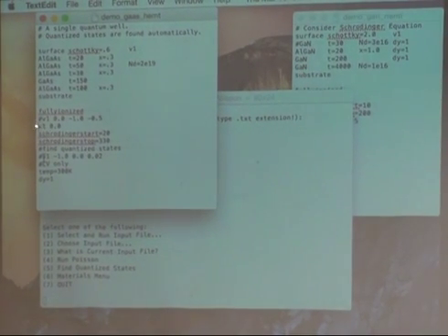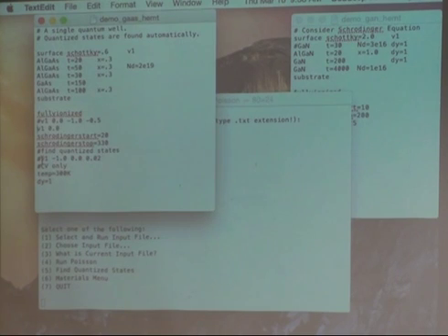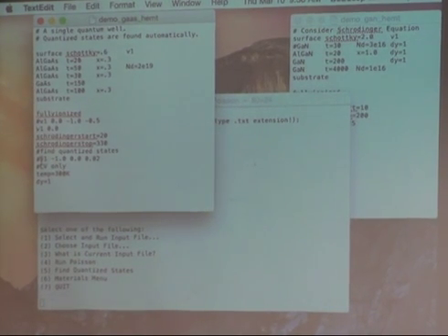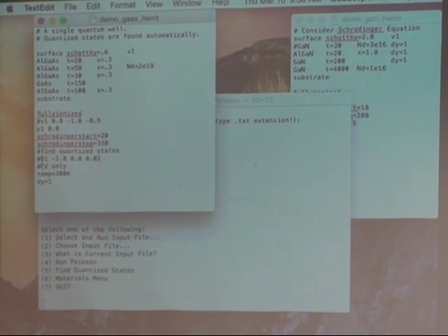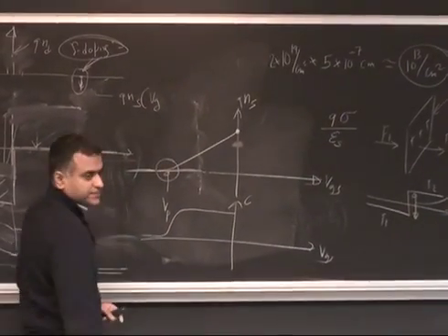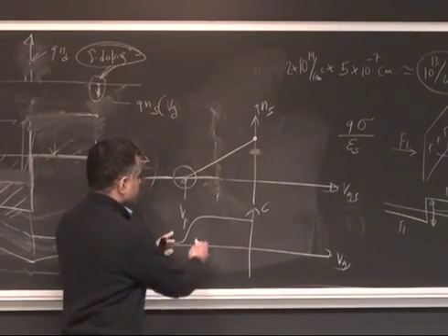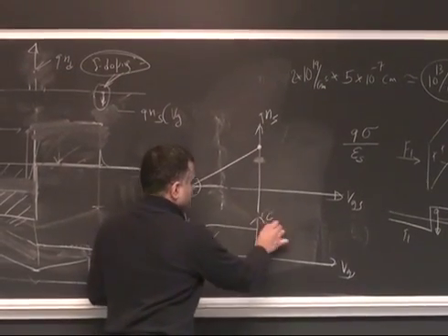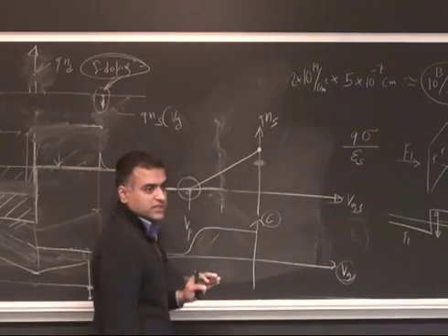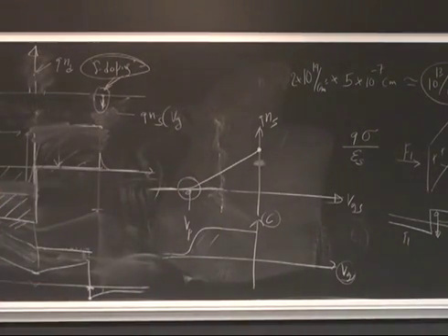You can turn this off and say, well, I want to apply voltage now. I want to sweep the voltage from -1 to 0 volt at steps of 20 millivolts. You can ask that, and it will show you two things: your capacitance versus gate voltage, which I'm going to sketch now, is going to look like that. The capacitance versus gate voltage, and the carrier density is an integral of this charge, basically the integral of CV. It's not exactly linear, but close.